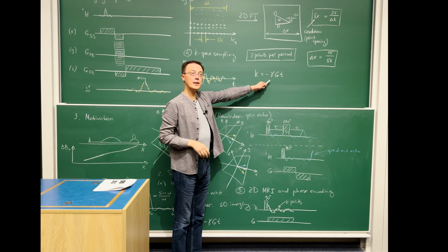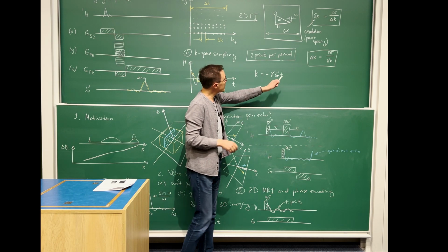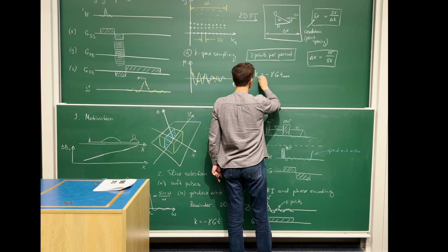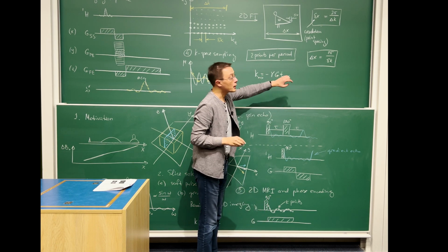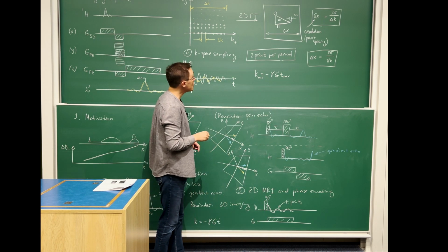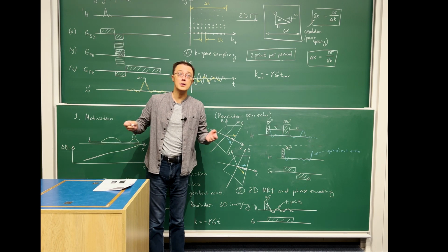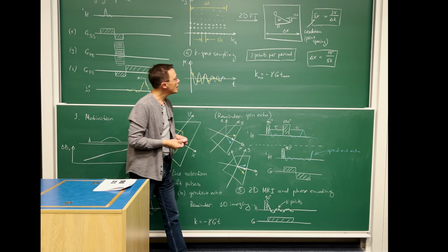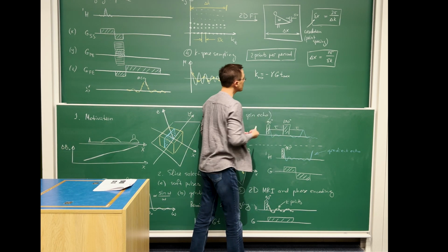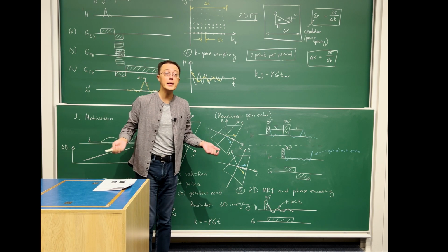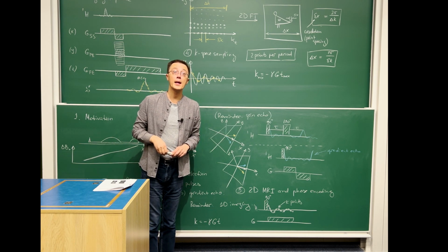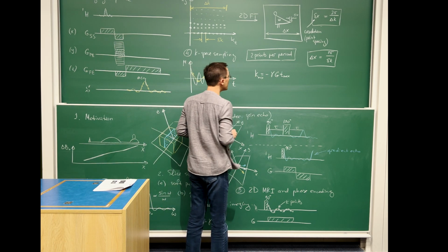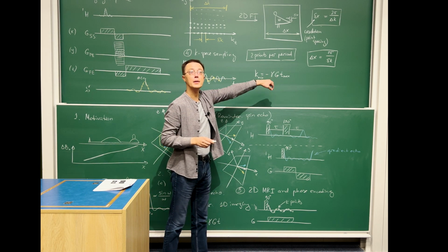Gamma we can do nothing about. Interestingly, T max, right, so that's K max, we also can do nothing about, because the magnetization inevitably relaxes. It has a T2 time, and the T2 times are in the hundreds of milliseconds, and so the longest T we can afford to sample before the magnetization is completely lost is also fixed. And so the only thing here that allows us to make this k bigger is the gradient amplitude.